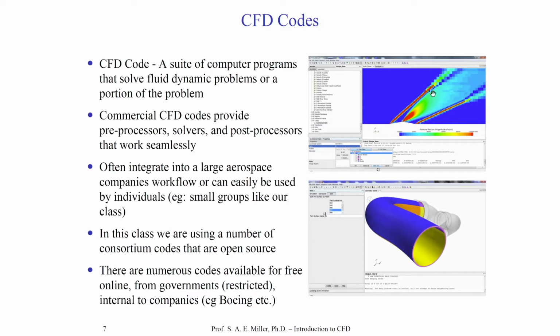This sort of larger contour range would be an expansion wave. And then this little corner here, which the flow turns into itself one more time, would be a second trailing shock wave. So this is a typical supersonic flow problem where we have some analytical solutions, for the inviscid case at least, meaning there's viscosity set to 0, and it's solved with Star CCM.